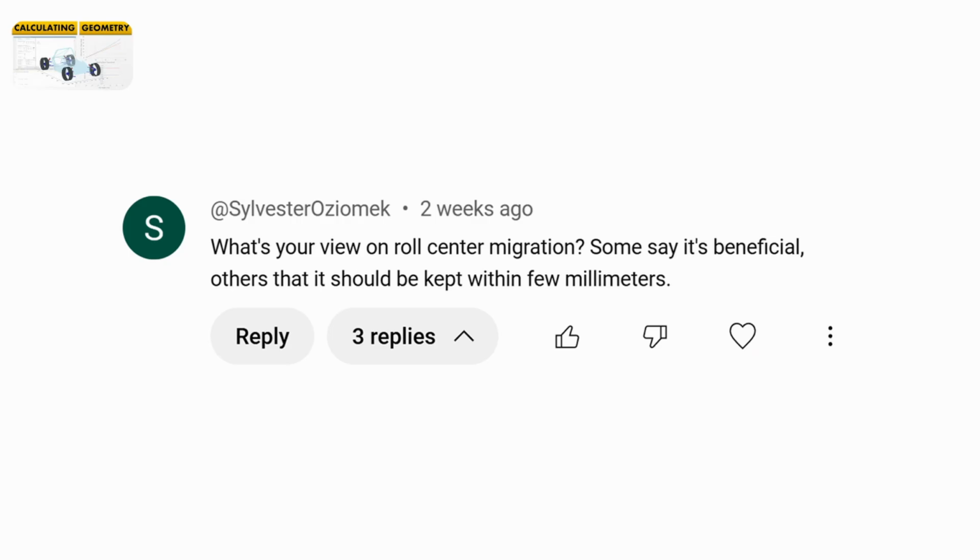Now, on the video about calculating suspension geometry and some of the experience that I've had in the past, really running through the different things that I've applied with analyzing pure kinematics, one of the questions from Sylvester Oziomek, hope I pronounced that correctly, was what's my view on roll center migration? Some say it's beneficial, others that it should be kept within a few millimeters. Well, it's a very controversial topic. A lot of people have written about roll centers and roll center migration in the past, and I think some of what has been written has been a little misguided.